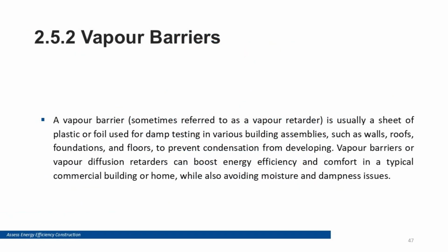Vapor barriers. Vapor barriers or vapor retarders limit water vapor diffusion through building assemblies. Correct use depends on climate and construction type. They must be coordinated with insulation placement, airtightness strategy, and ventilation, so moisture is controlled without trapping water in cavities.